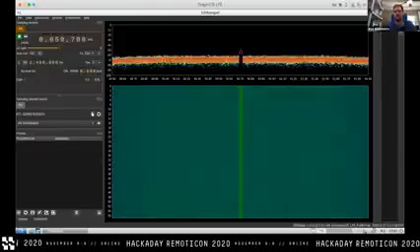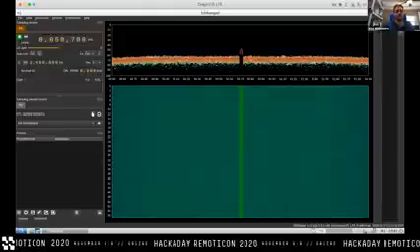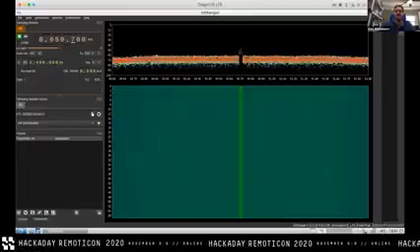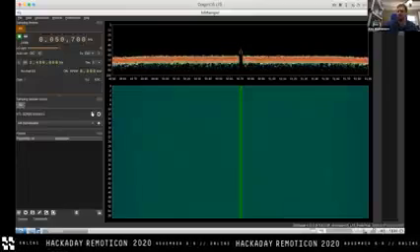Turns out it's still not altogether that useful, but getting close. It's definitely a lot more useful for certain applications where, if you're hunting around for sub 100 megahertz noise, cool, you can see nearly all of it between 30 and 100 megahertz in one capture on this guy.